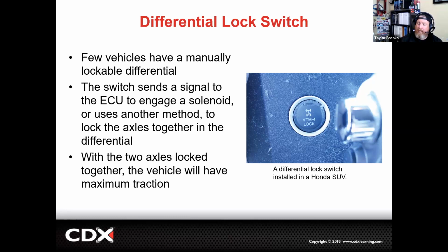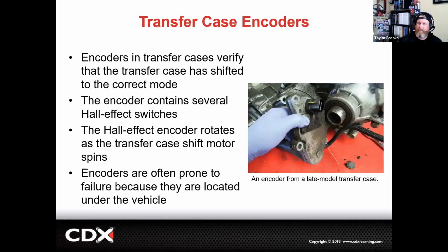Occasionally, we can have a locking differential inside of our transfer case. Now, we brought that up when we were talking about transfer cases in a later chapter. But what this allows for is equal torque to go to the front and to the rear. So we'll see these on four-wheel drive vehicles and not all-wheel drive vehicles. Again, once the operator hits that switch, as long as the vehicle is operating in the correct operational parameters, it will lock that center diff.